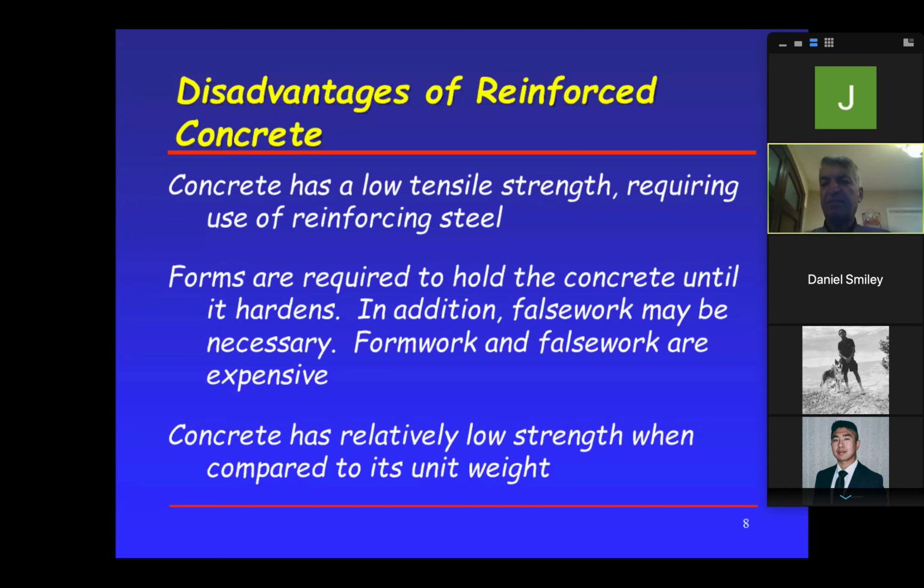We have something called slip form. That means, let's say you're building a wall. You have a form that you put the wall in, and then when you're done, you slip it up another floor. You pour it, you slip it up another floor and pour it. So all kind of form work out there, but it is very expensive.